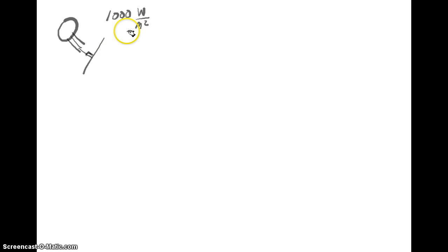Now, I want to talk about a phenomenon. As the sun transits in the sky and moves going up, it is no longer 90 degrees to the solar panel. There's some angle here, theta, and it turns out that the energy that we can recover from the sun is a function of the cosine of that off-point angle. We will need to know about those angles shortly.